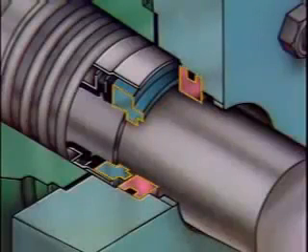Each element has its own seal ring. The two rings are positioned close together to form a seal that has virtually no leak-off. To prevent the seal rings from being damaged, some type of lubricant must be supplied to them. In some applications, the process liquid being pumped is used as the lubricant, but that's not always the case.